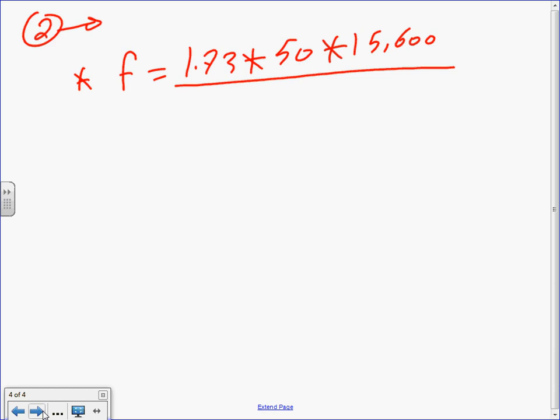Okay, so what's my multiplier for 250? 18593. Any question, guys, about the 18593? This is your multiplier coming for this particular cable, for 3 conductors in 1 PVC conduit. If you're using rigid or EMT, you're going to go under steel conduit.